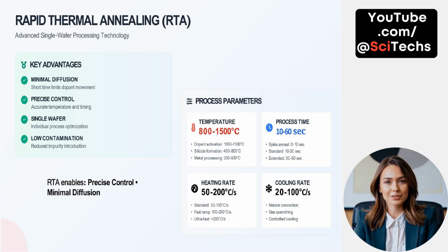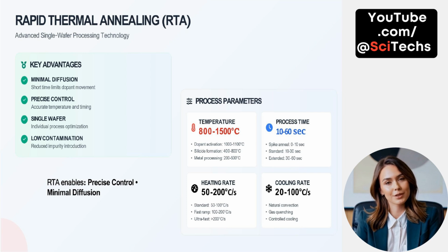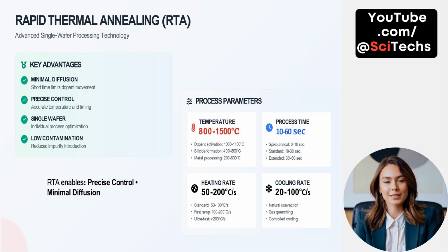RTA also offers precise control. Temperature ramps and durations can be finely tuned, enhancing uniformity and repeatability. Processing one wafer at a time allows optimization tailored to each wafer's requirements. RTA also achieves low contamination due to reduced contact and better environmental control. Typical processing temperatures range from 800 to 1500 degrees Celsius, with specific windows for dopant activation, silicide formation, and metal processing.